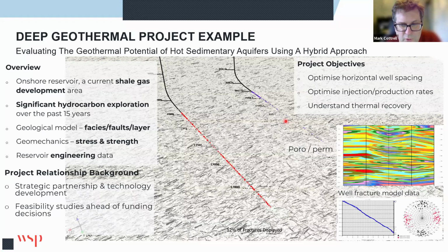Those implications could be, well, the colder fluid that we're injecting doesn't have enough time, doesn't have enough contact with the reservoir rocks to actually conduct some of the heat. So the fluid that we end up producing could be cooler than what we need. Obviously, if we space the wells too far apart, then we risk not having hydraulic connections between the two wells. So it's very important to locate and offset these wells properly.